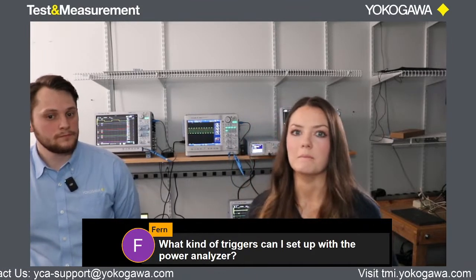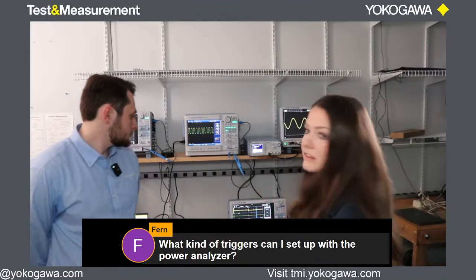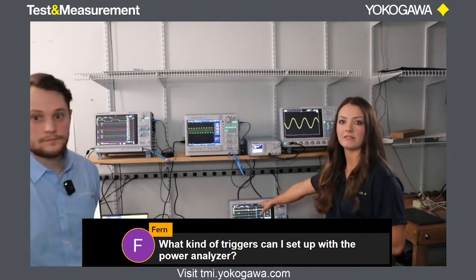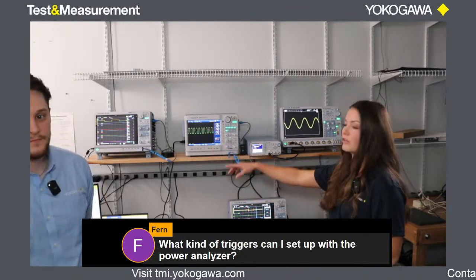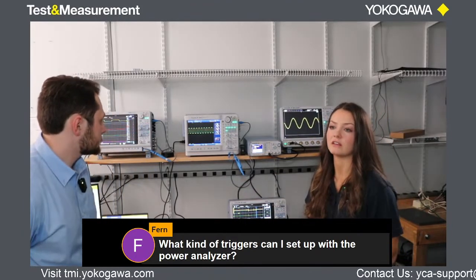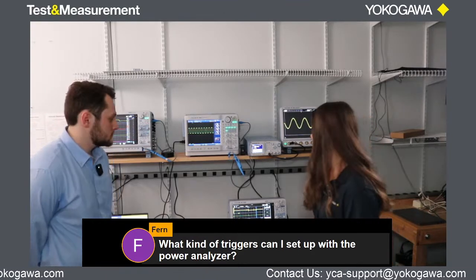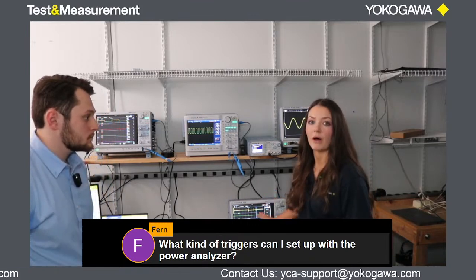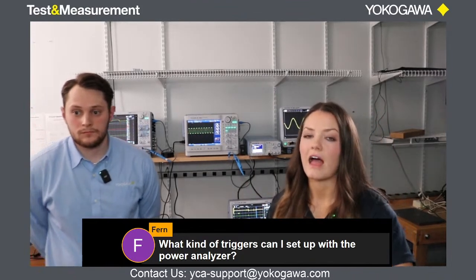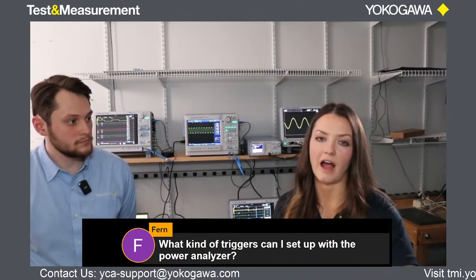But really, for triggering, that's more of our scopecorders or oscilloscopes. That's a DLM 950. I think you can see it back here. This is our oscilloscope, the 950. We actually have another 950 over there. Those are triggerable instruments. They have advanced triggers that you can set up. And like we were talking about earlier, if you really wanted to trigger off of power data, you can do that really well with the 950, and you can synchronize this waveform data with the WT5000, so you can get those triggered waveforms as well as your accurate power data.